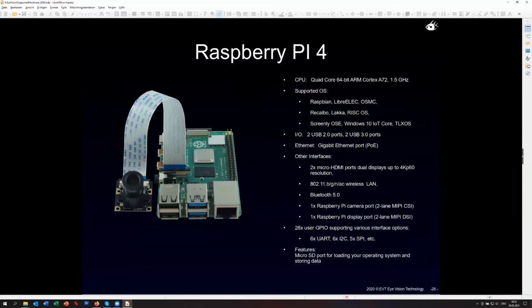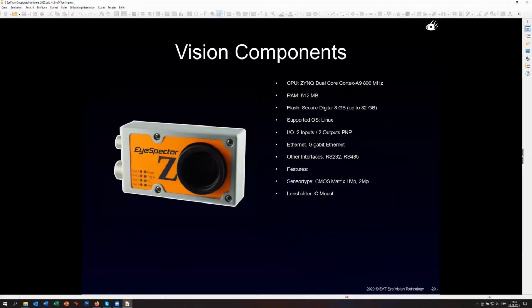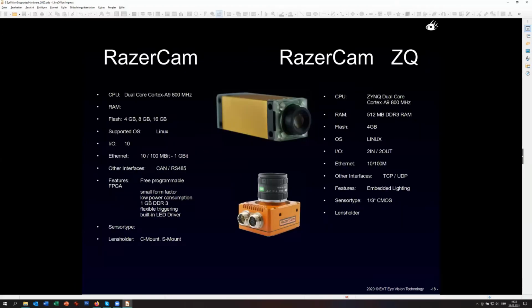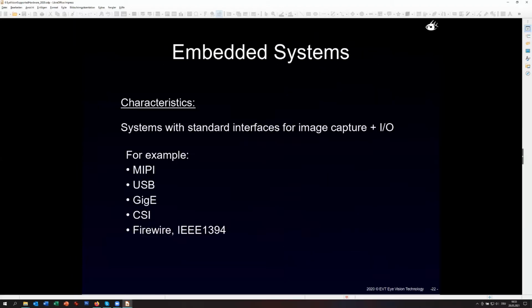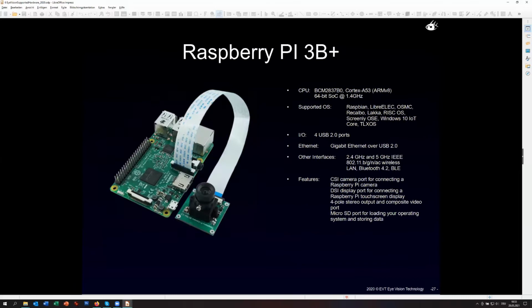And the connection, as you can see, on all these platforms there is an Ethernet connection, which is currently the main communication channel which we use to the robot. We can also support the RS232 interface, as long as the hardware platform supports it. All these platforms mostly have it, or you can add it with an adapter. The smart cameras which we saw before, most of them have an RS232 interface, so you can use RS232 as long as the robot supports it.